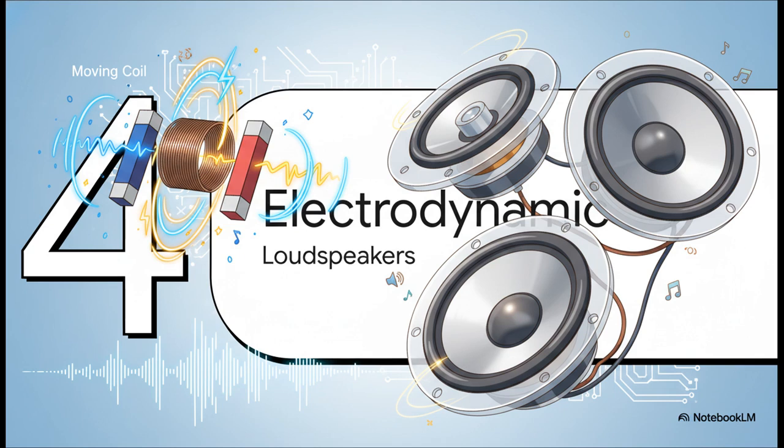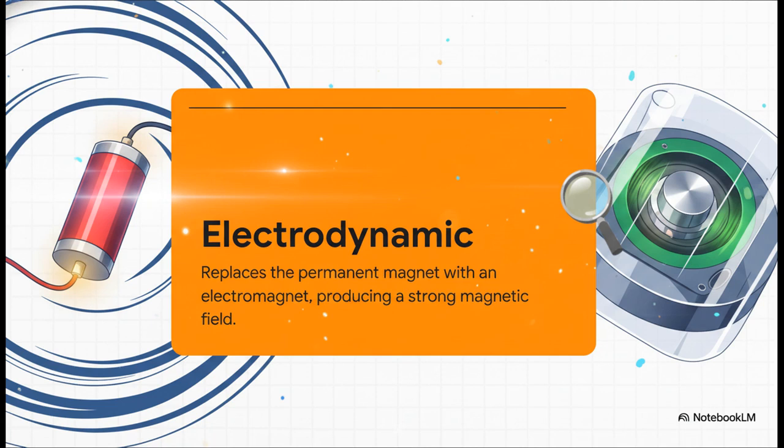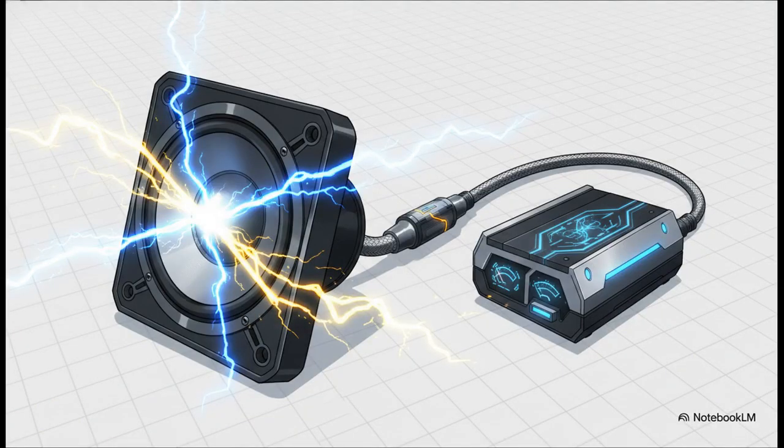Moving systematically to Section 4, electrodynamic loudspeakers. Here is the defining textbook difference. The principle is essentially identical to the moving coil, but it replaces the permanent magnet with an electromagnet. A field coil wound over a central limb produces a very strong magnetic field. Think about that distinction for a moment. Because we have replaced that permanent magnet, the features change dramatically.